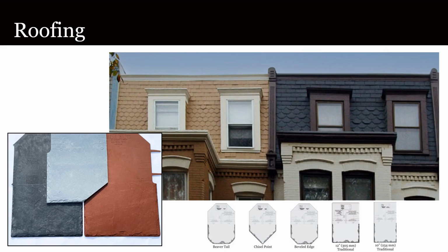These polymer products are molded to mimic the irregular profiles created at the edges of real slate shingles when they are cut. Different manufacturers offer different shapes, but only one manufacturer offers slates that are narrower than the 12-inch standard shingle that most are produced in. And all the widths that they do offer are the same length, creating some inefficiency for matching smaller slates that have a proportionately shorter exposure. Other companies offer multiple widths only as a blend, intended for creating a picturesque or rustic effect.